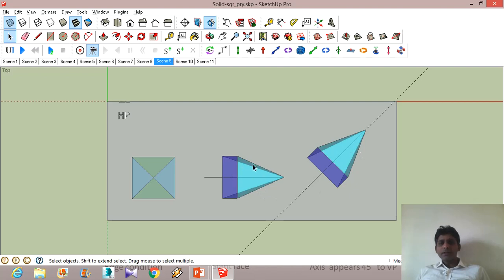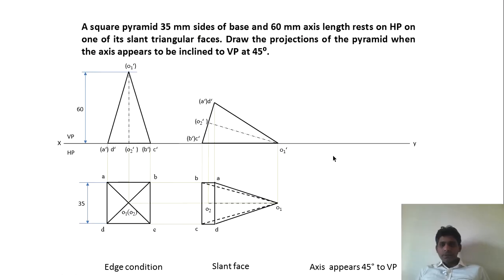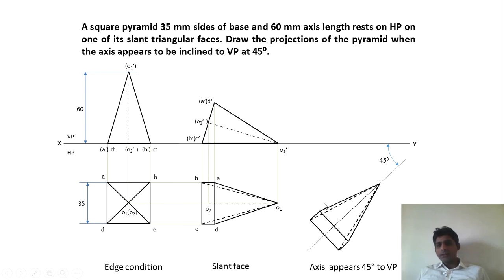So you have to reconstruct this particular view here. So we have to draw a line at 45 degrees and we have to reconstruct this view here. To reconstruct, I insist that you mark one point O1 here, O1 here, and O2, O2, and with respect to these 2 points, you can measure all other points and get the intersections and join the intersections respectively.